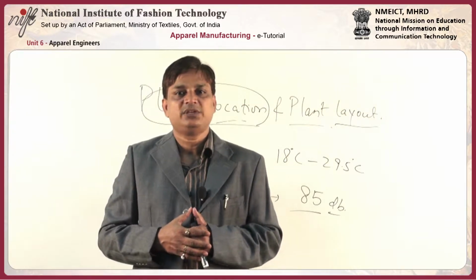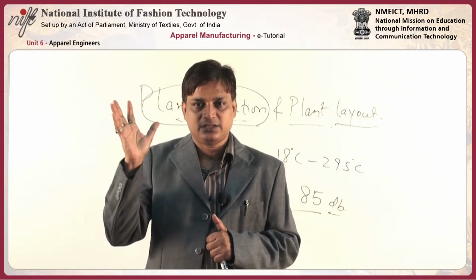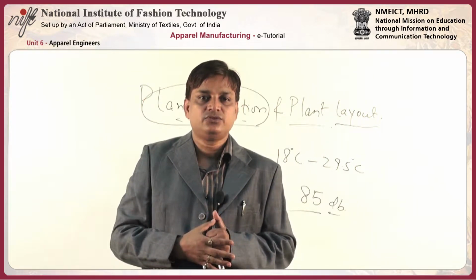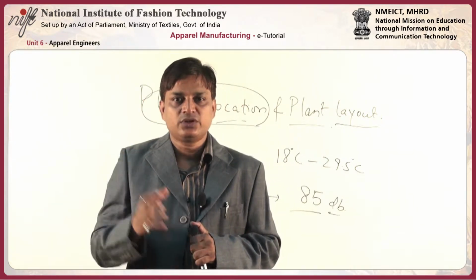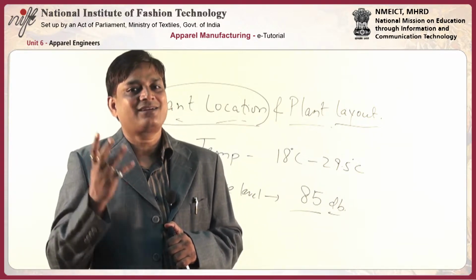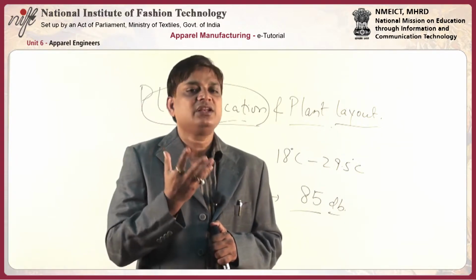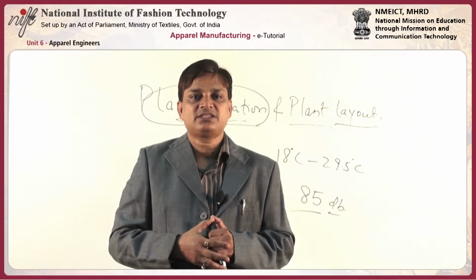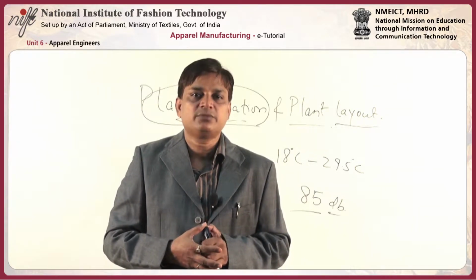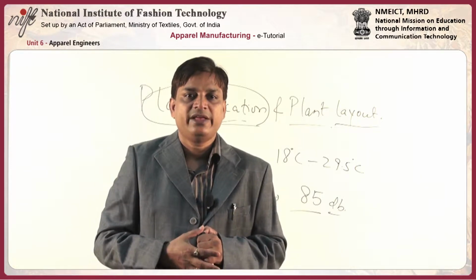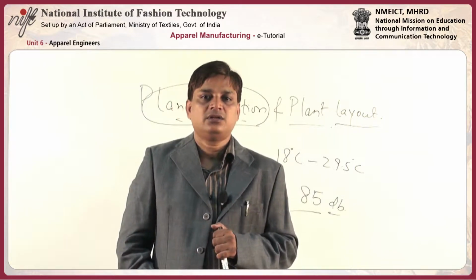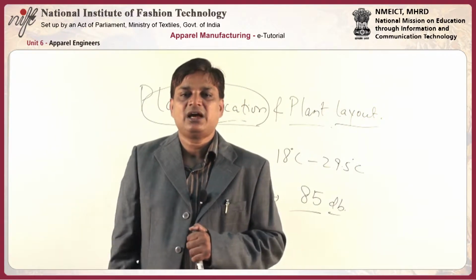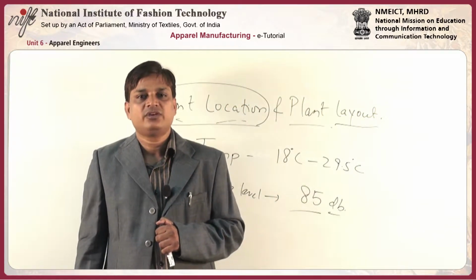All emergency exits are to be equipped with emergency lighting. Emergency lighting should be on the emergency exits and all exit doors, and should provide at least 60 minutes of power backup. Fire alarms should be placed on each floor, and emergency lights should be placed above exits and on the stair walls. Whatever alarm is there, it should be audible throughout the factory.